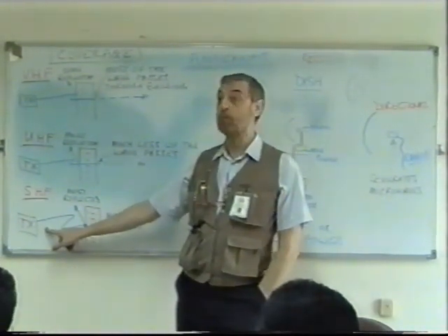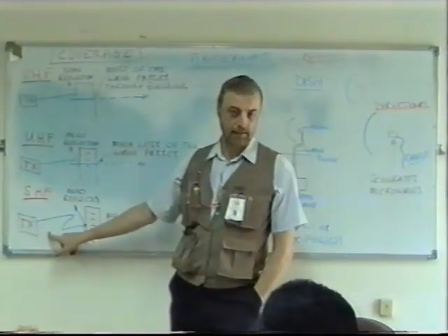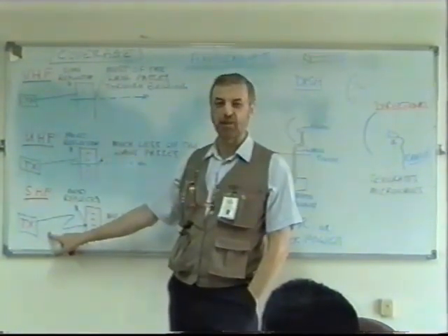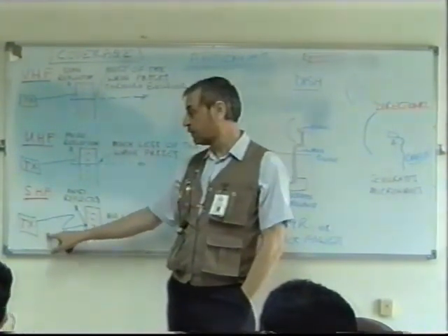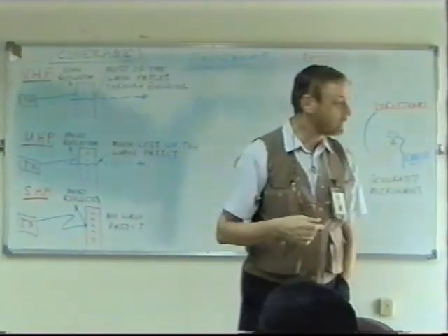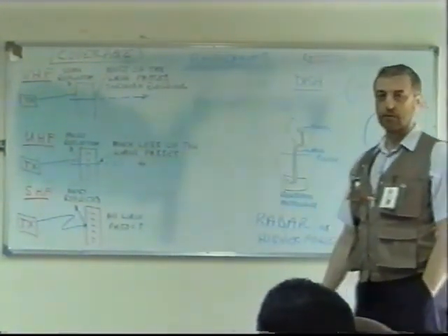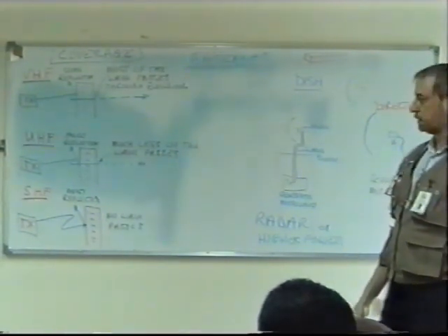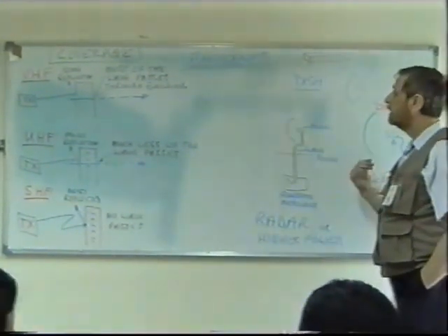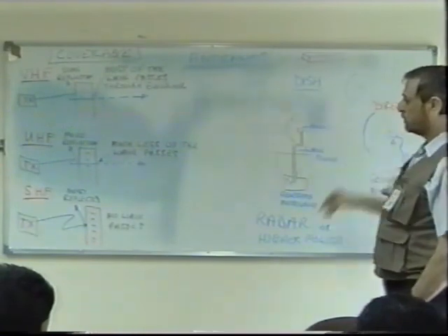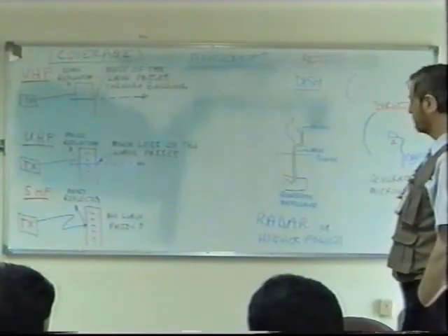You would never use this for mobile radios, unless it's satellite, right? But that's a special case. Normally, what you would use this for is, instead of using cabling, a direct point-to-point microwave link, what they call a microwave link. Satellite's a special case. Finally, the other type of antenna is the dish, which we would use at SHF because we want to make it as directional as possible.